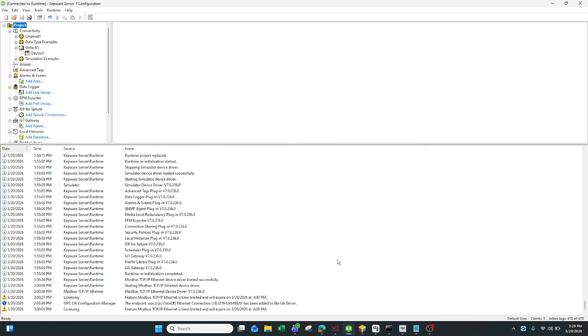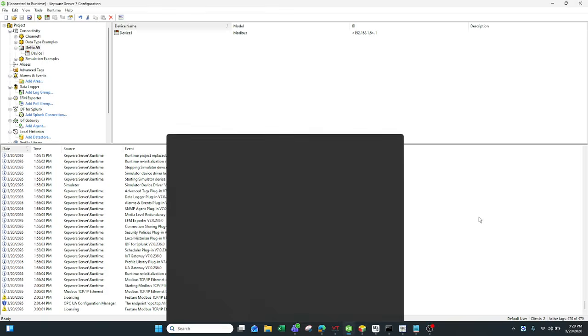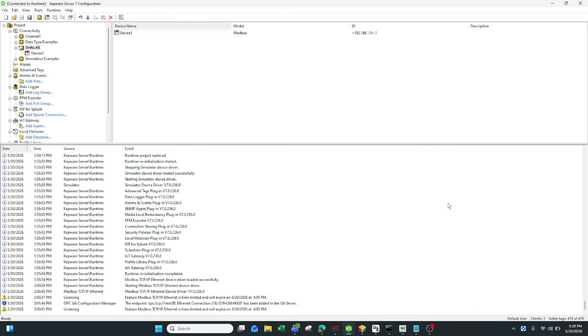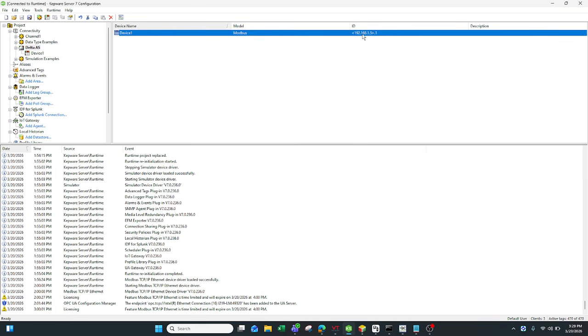Right now we are also running another server, which is holding the secondary OPC UA server, and on the secondary OPC UA server you also need to do the same setting. Then in the OPC UA Configuration Manager, you need to get the URL link from the secondary OPC UA server. It needs to be in the same loop. So this is all the settings in Kepware.